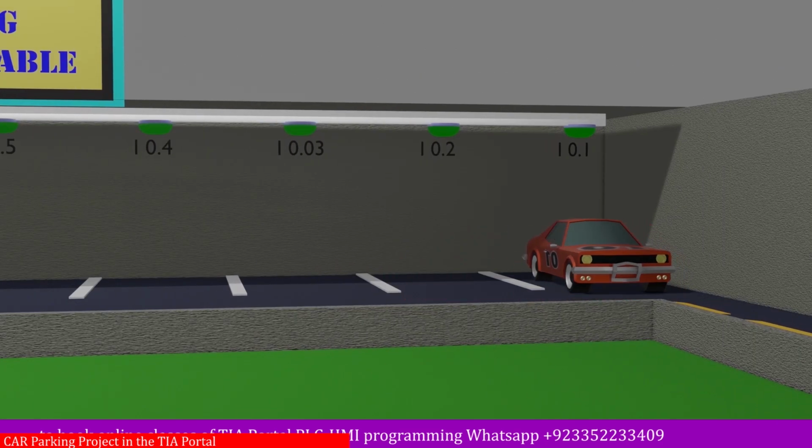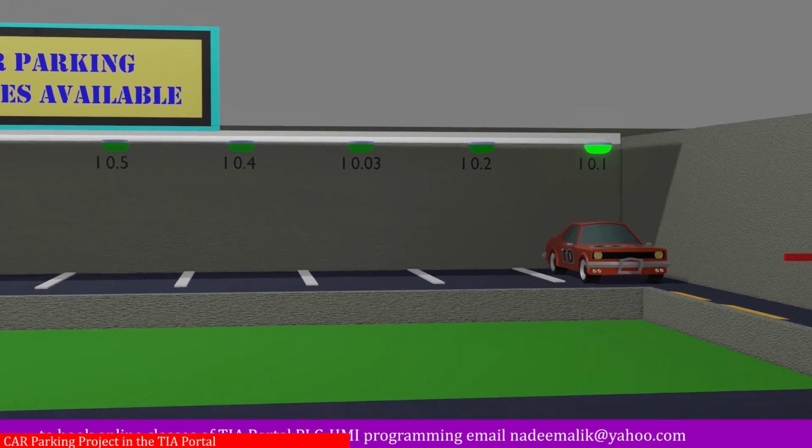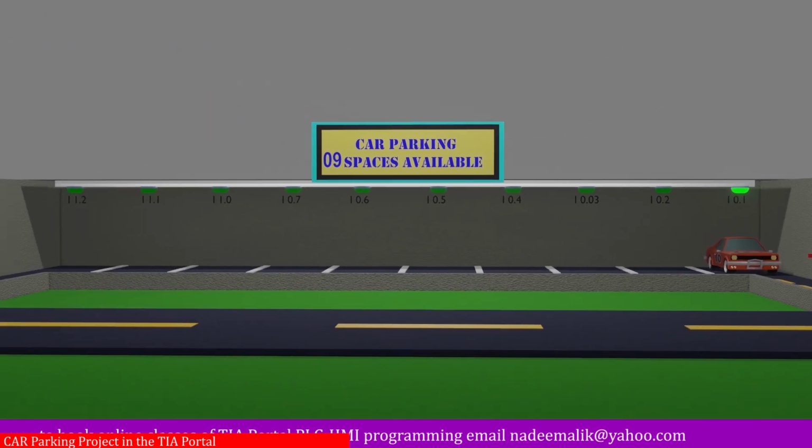As you can see, each parking space has a sensor and each sensor is connected at an individual PLC input. The sensor for the first parking space is connected at I0.1 input of the PLC and the sensor for the last parking space is connected at I1.2 input of the PLC. There is a display on the top of the parking lot which is showing the remaining empty parking lot spaces.